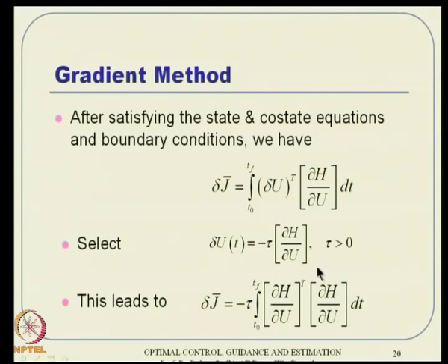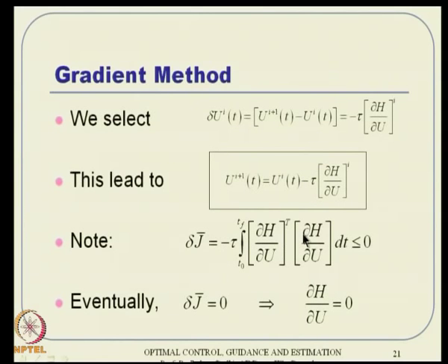At every grid point of time, we will compute this delta u that way, and then update the control trajectory like this. The delta u_i of t is nothing but that, and it is already available; we just computed it that way. If I equate these two, then my updated control history is nothing but that. Running over every grid point in time, I will be able to compute it that way.